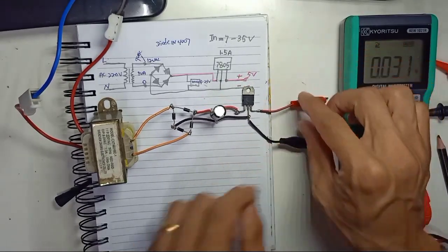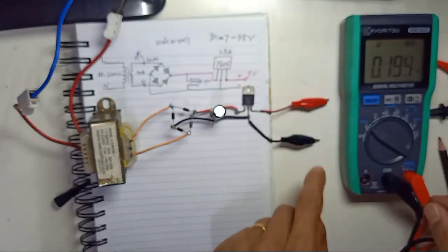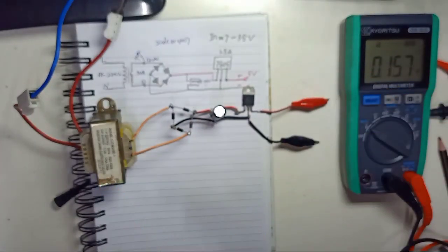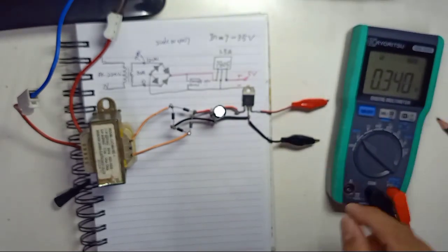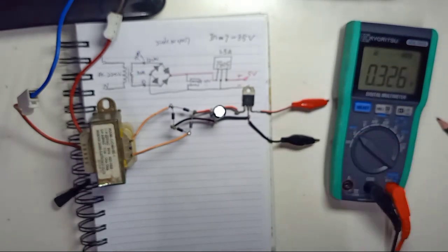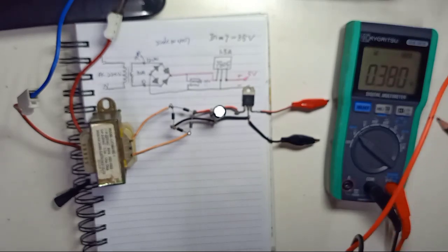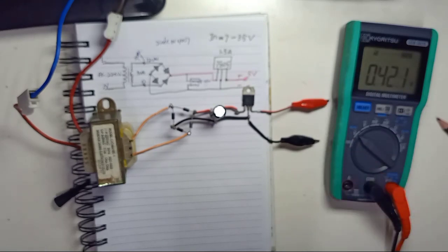After you already connect the AC power to the transformer, you don't touch your transformer. It's dangerous, and we're going to make sure how many volts the transformer input is. We select the AC mode here, and I turn on the power. And make sure you don't short the negative and positive of the output.